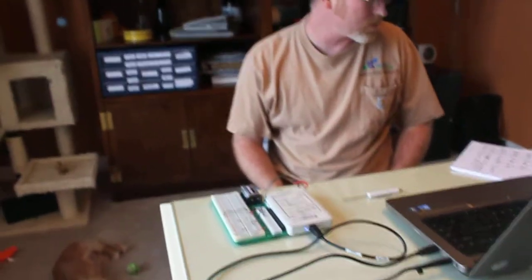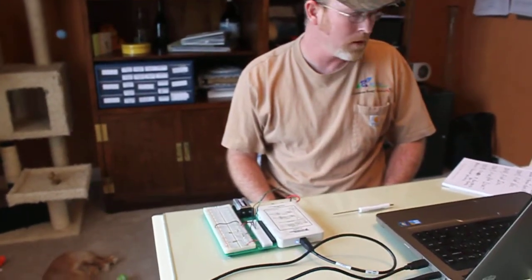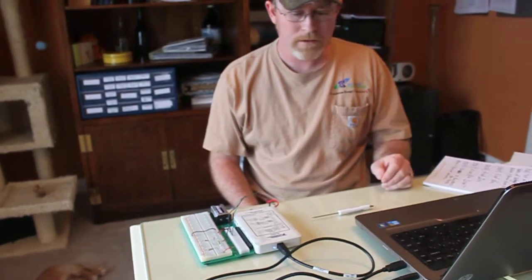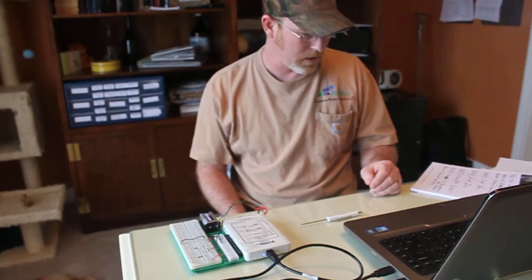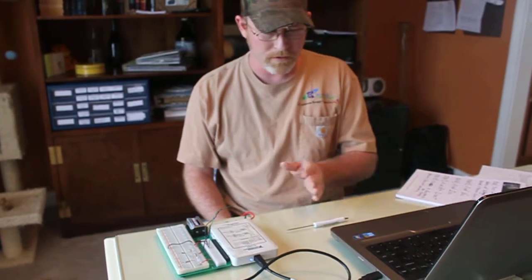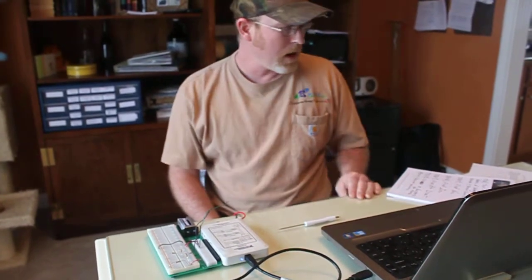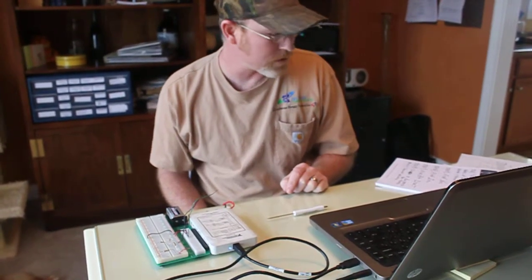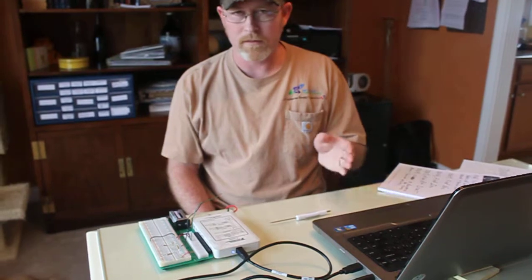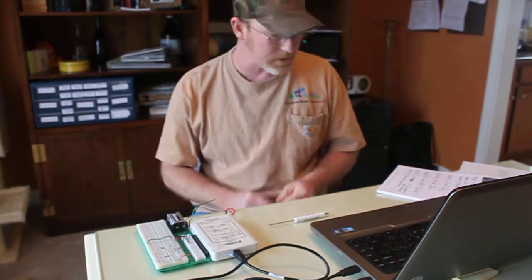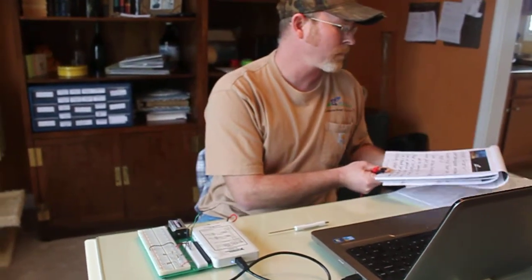Last, we're going to try and prove the maximum power transfer theory. And the way we're going to do that is we're going to choose 10 different resistors from 0 to 5.6 k ohms, and we're going to see how those values match up as we come through there. First thing you need to do, in the first part of the demonstration, is measure whatever values of resistors you're going to use. You need to measure their actual resistance and record it prior to putting them in the circuit.